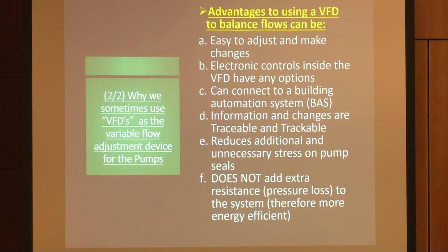So it is something that engineers, design engineers, are still installing the triple duty valves just because I guess everyone's just so used to it. And they don't want to break tradition and not have the triple duty valve. But at some point in the future, I think that will stop, because triple duty valves are expensive. And if you don't need them, why install them, right?